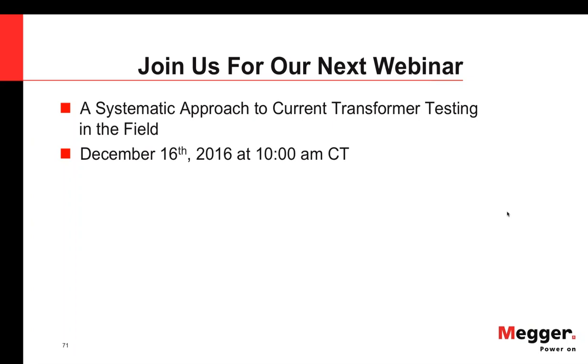All right, the next question is, have you seen any connection between harmonics or other power quality issues at wind farms and failing transformer bushings? Transformer bushings, that I haven't seen. I've seen issues with cable splices and things like that with the harmonics. I haven't experienced the bushing failures because of that. Doesn't mean this doesn't happen. It's just I haven't seen it.